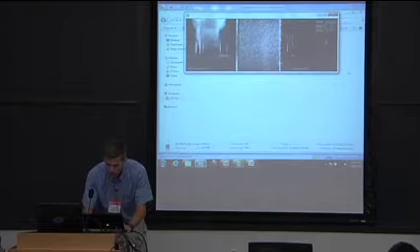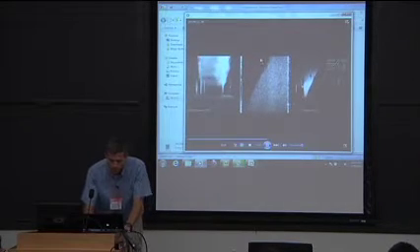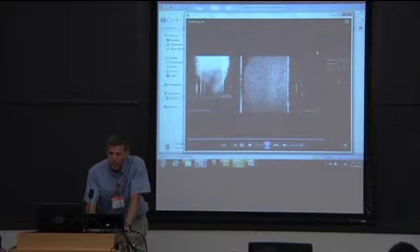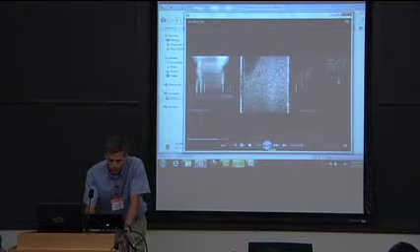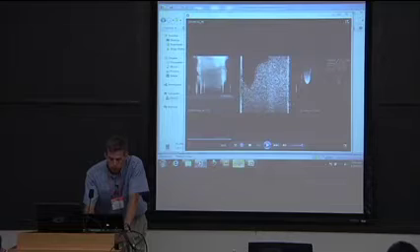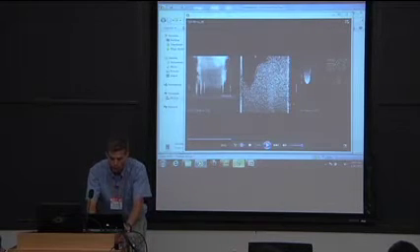It's looping right now, so let's just look at it. Here that flame is shooting upstream in the boundary layer. What you're seeing over here is CH chemiluminescence. So here's the flame, shooting upstream. There you see the chemiluminescence, the light emissions telling you that you've got combustion going on in this region.